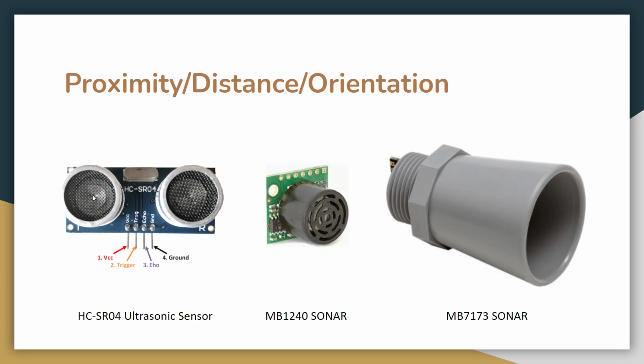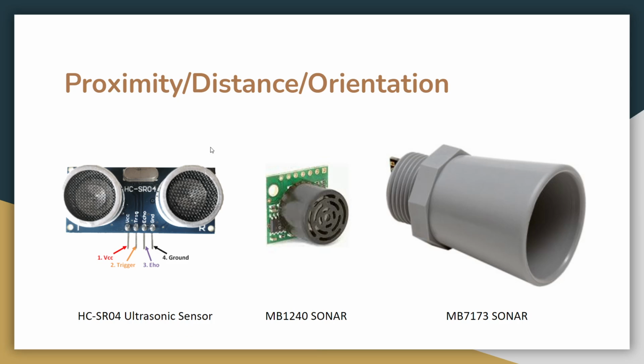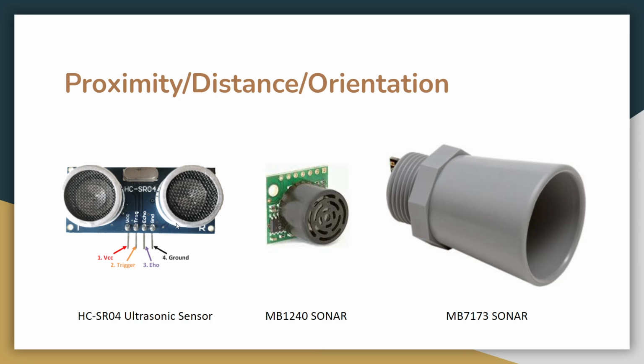So we keep an obstacle in front, and once the emitter emits the sound, it gets reflected back onto the emitter itself, or maybe over here, but it won't really reach the receiver. So that's not going to work out. So there is a minimum range for this sensor, so that it can detect something only if that something is kept at least a fixed distance apart from it, and there's a maximum range. This applies to all three sensors actually, not just this sensor.